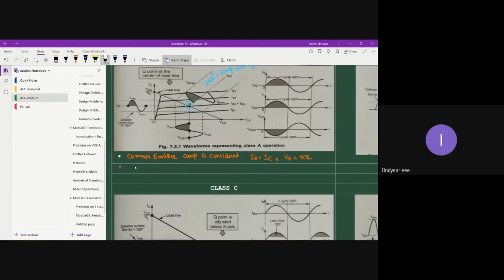So that's because common emitter configuration gives 180-degree phase shift between Vi and V0. That's the reason normally, while sketching the waveform, voltage signal is drawn from negative half cycle. So first half cycle going to be negative half cycle, followed by a positive half cycle.